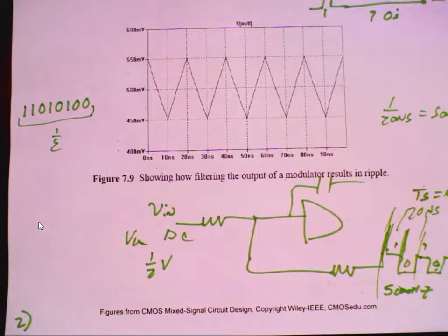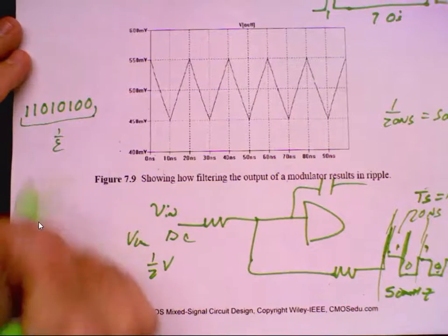Yeah, you have two feedback paths, both inputs are two, you randomize things, and so it's harder to get the repeating tones. So tones in higher order modulators, third, fourth, are just not an issue. They're really not an issue in second orders. They are an issue in first orders because, in the ideal case, you get things just repeating over and over again, okay?